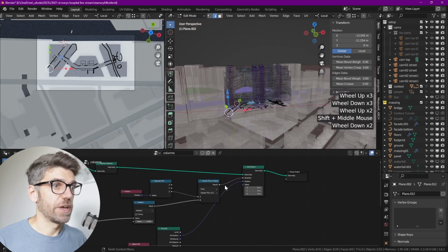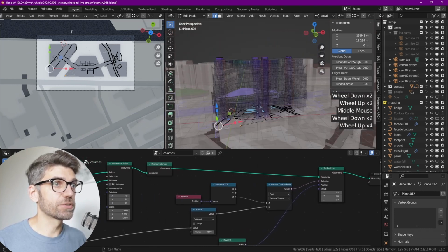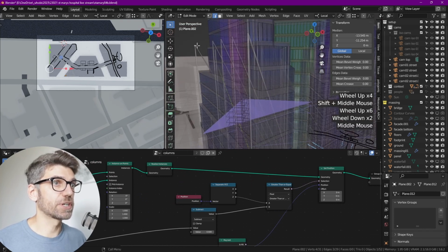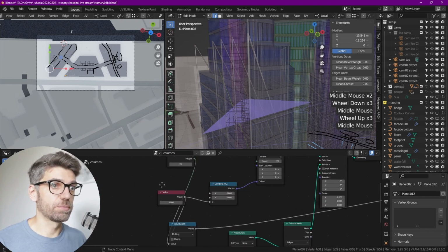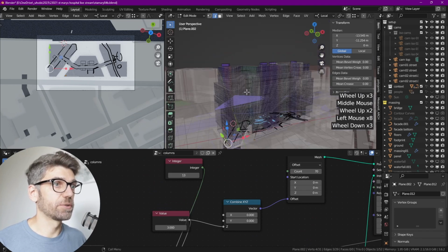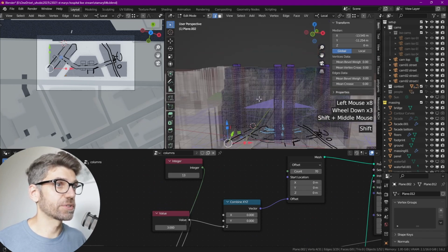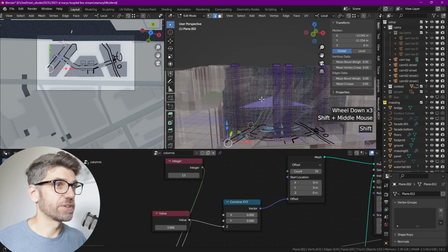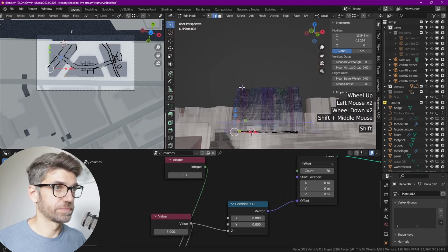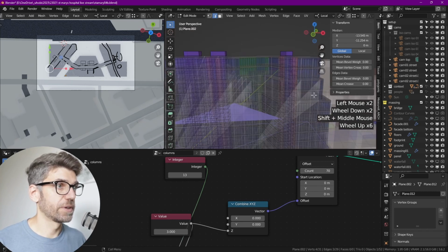And yeah, I think we have to go down because we still might have too many floors in here. And yes, that's where the issues are coming. You see, those are too high. So let's bring this down a little bit more by reducing the number of subdivisions until we stop having those kinds of funky situations happening here. Okay.